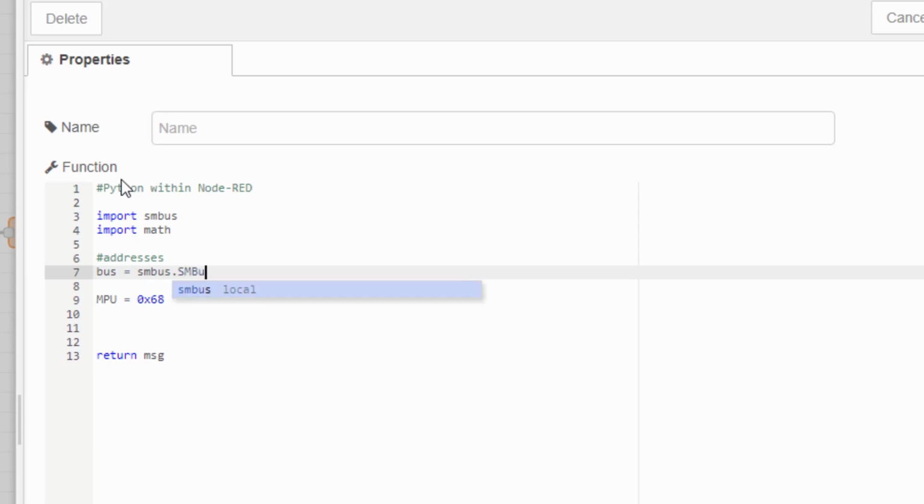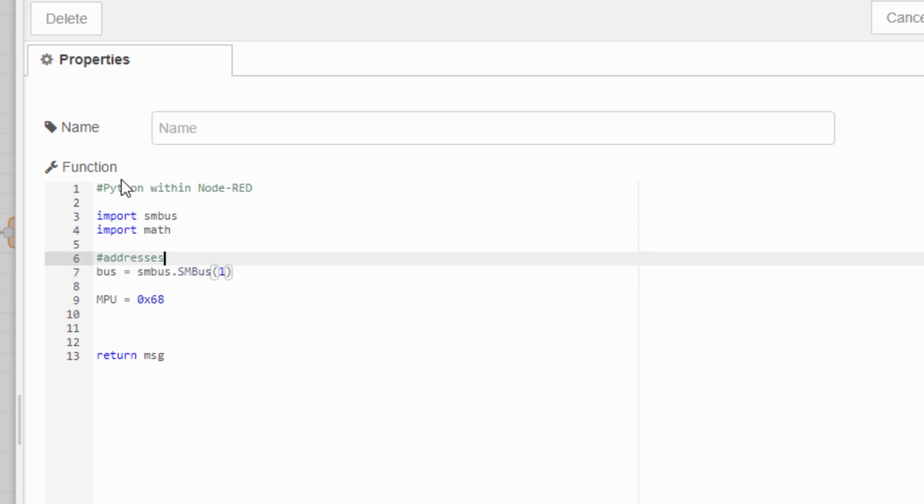I will show you this in both ways, with our defined bus constant, but you can also see how this is working usually. So that's valid for all modern Raspberries. Raspberry 3 and 4, it's always 1. And then we should take also the registers we want to read out, but maybe we do this in our first example without definition, we do this directly.